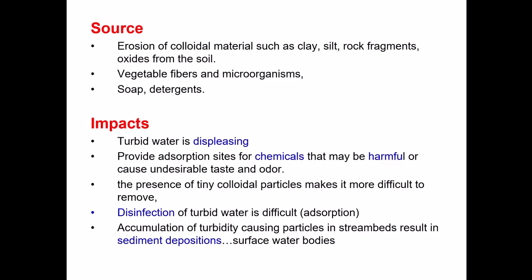So for revision, if we talk about the impacts of turbidity on water and its treatment, first, turbid water is simply unpleasant. People usually don't want to drink or use cloudy water. Second, fine particles, also called colloids, can carry chemicals and microorganisms, some of which can be harmful. Third, turbidity makes disinfection more challenging. We use chlorine to kill microorganisms, but when colloidal particles are present, some of the chlorine reacts with these particles instead of disinfecting. This means we need to add more chlorine, like giving a sick person too much medicine.